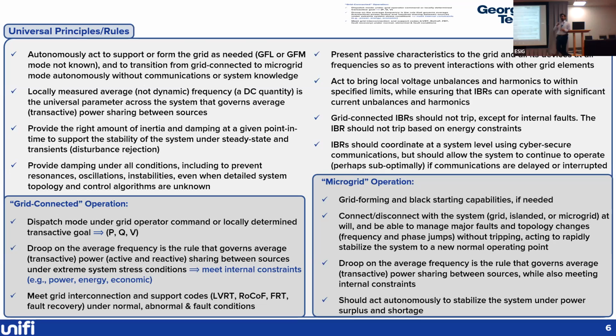But since here we are talking about grid forming inverters, that's something that we want to really operate. Now, we spoke about droop, we spoke about sharing the power burden on the system, but at the same time, we also want these inverters to be dispatchable. So if you have a system operator planning the next 1 hour dispatch, the operational horizon for the next couple of hours, the system operator needs to be able to send commands to the various inverter-based resource plants and say, okay, for the next 1 hour, we want you to operate at a certain P and Q level or a certain P and V level. So a grid forming inverter should also have the capability to be dispatchable in the near steady state requirement.